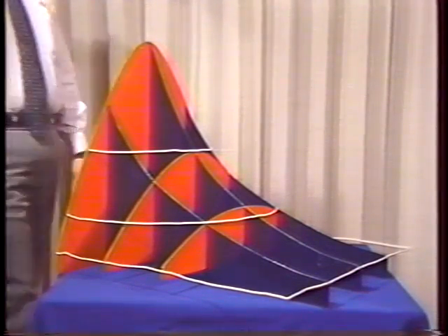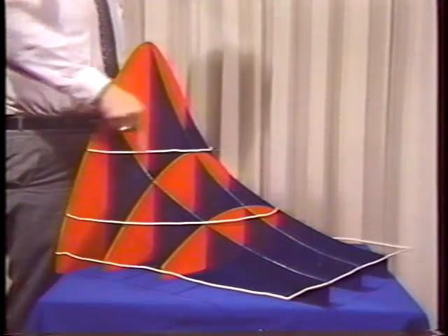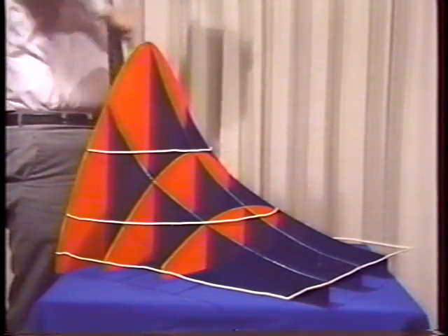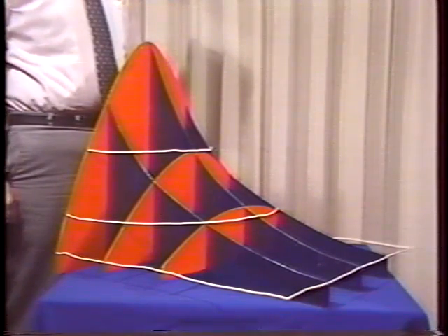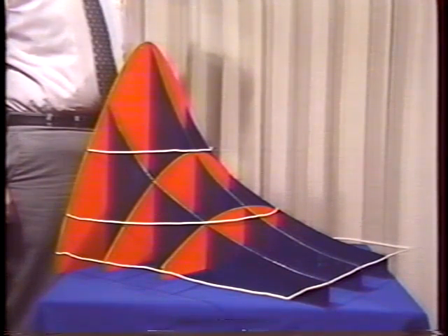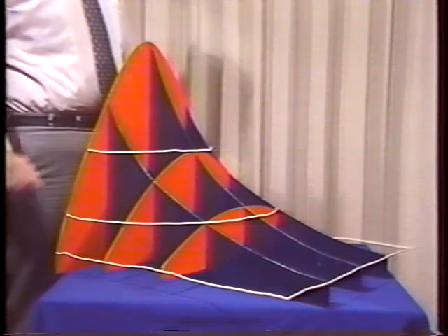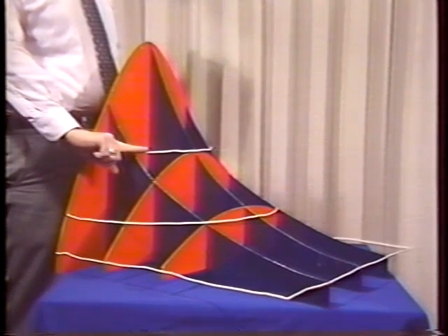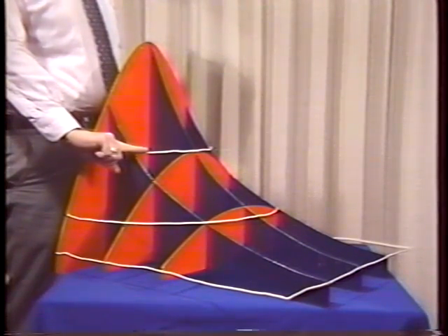In our model, lines of constant altitude are lines of constant vector potential. In two dimensions, lines of constant A sub z are lines of magnetic flux density. So the wires are the lines of magnetic flux density.